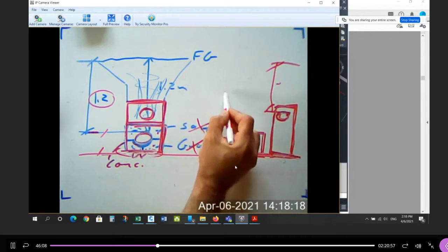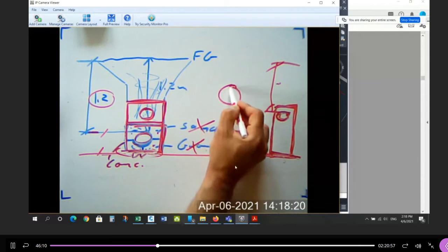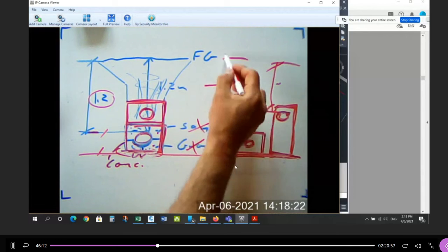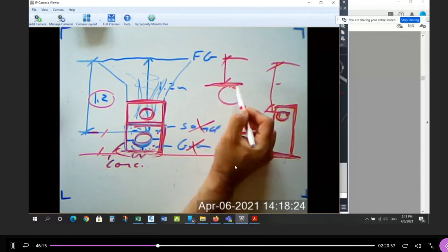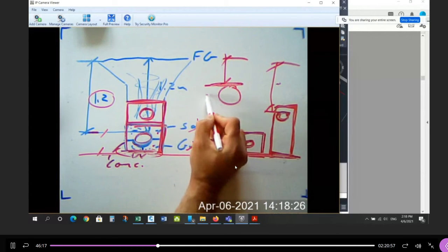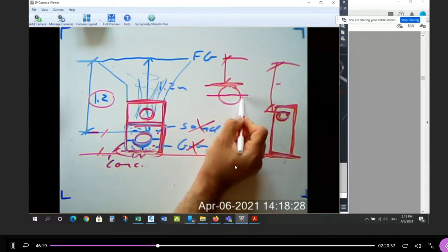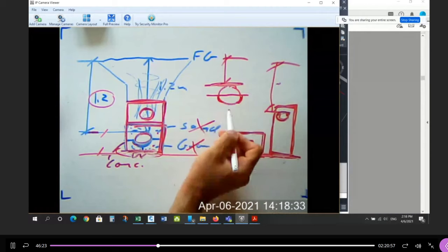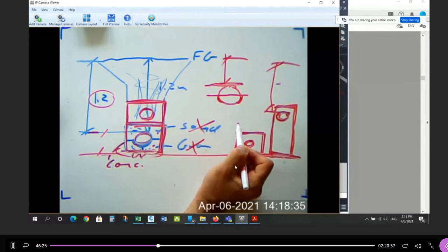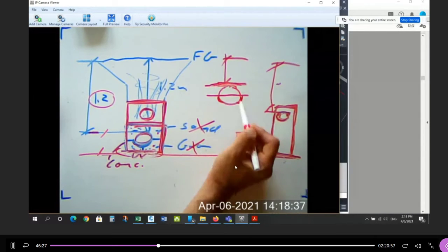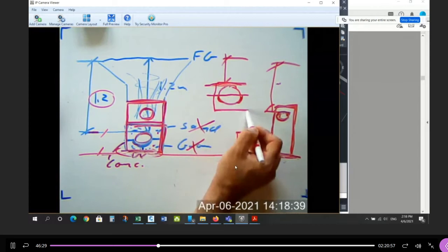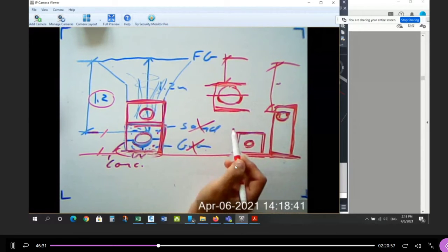And really, when we talk about frost protection, they talk about to the obvert, right? Make sure there's no frost here. Really, frost protection can go to the spring line of the pipe because it's not until you get underneath the pipe, right, that you actually start to affect the movement of it. So this is conservative, okay? But again, if you frost protect all the way to the bottom, then it's even better.